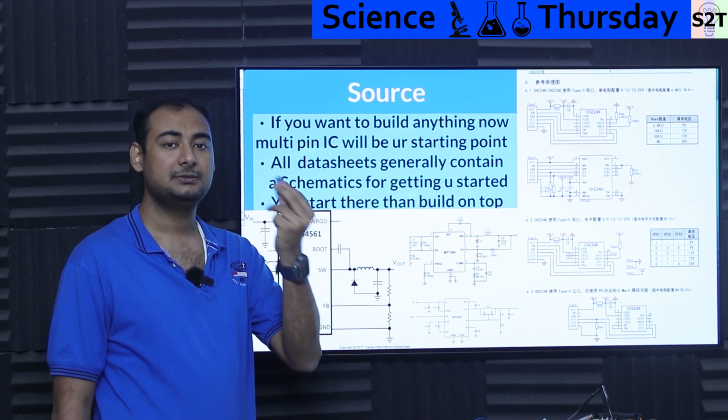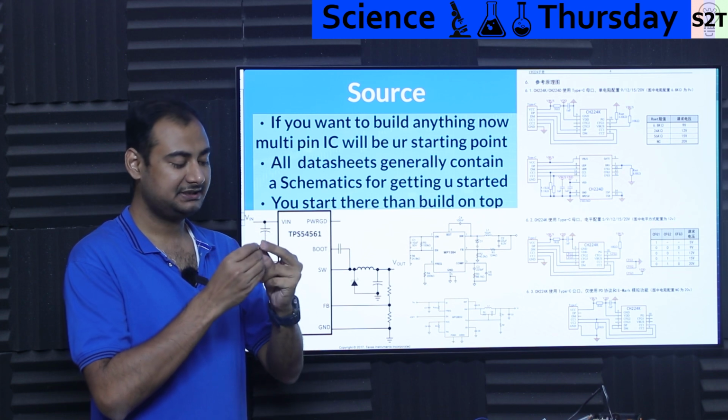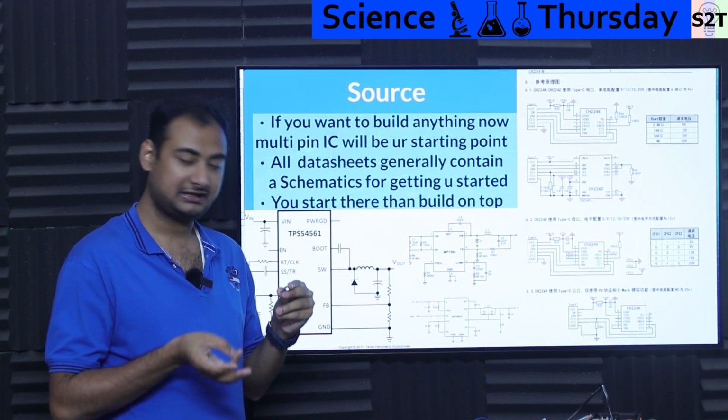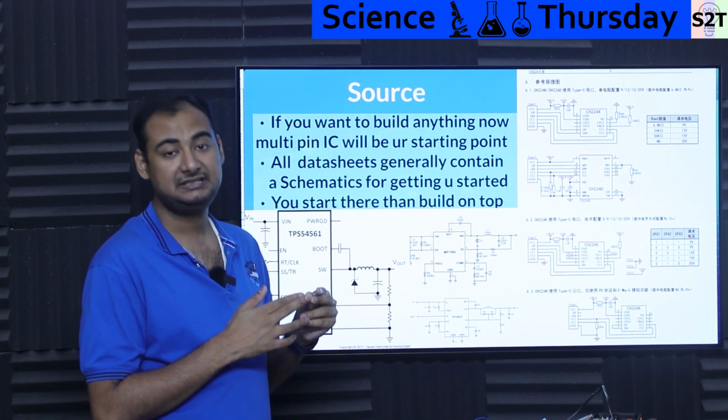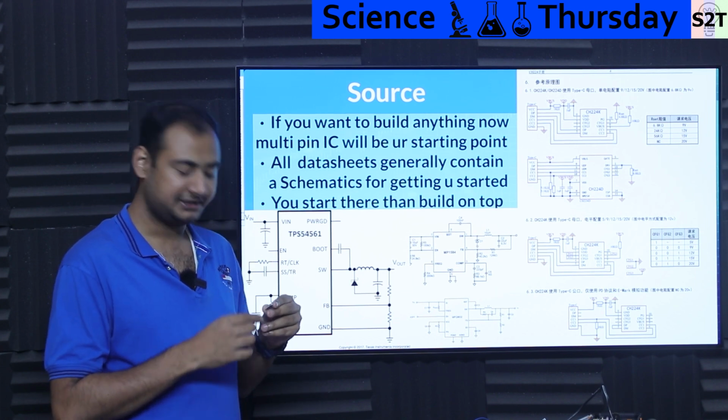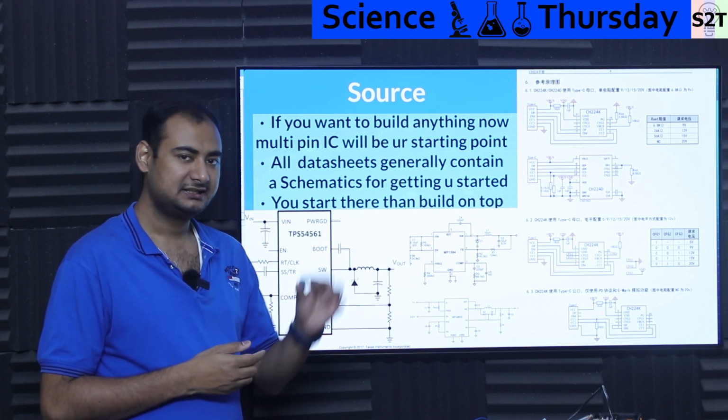this is a USB-C breakout board. I plugged USB-C in, it gives me outputs. What are the outputs? You have VBUS, which will be the positive rail. We have ground, which will be the ground. And we have CC1, which is a requirement for USB-C, and CC2, also a requirement for USB-C. And data plus and data minus. Okay, cool and awesome. But here's the, can I get...